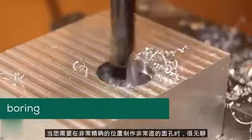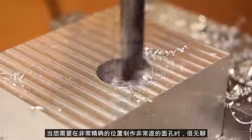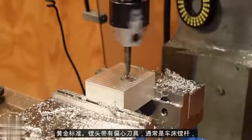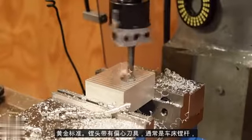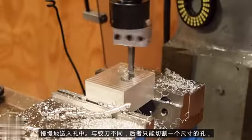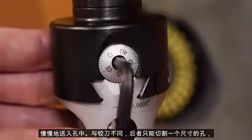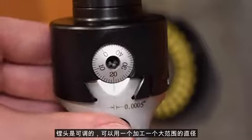When you need to make very straight, round holes at very accurate locations, boring is the gold standard. Boring heads feature an eccentric cutter, often a lathe boring bar, which is slowly fed into the bore. Unlike a reamer, which can only cut one size of hole, a boring head is adjustable, allowing a wide range of diameters to be machined with a single tool.